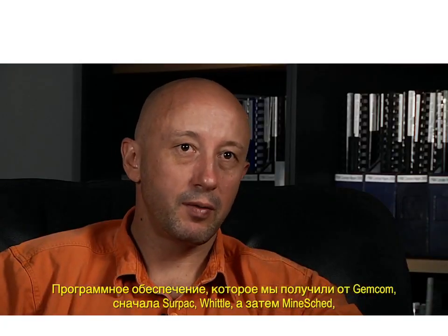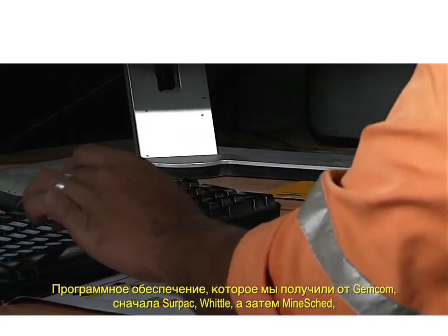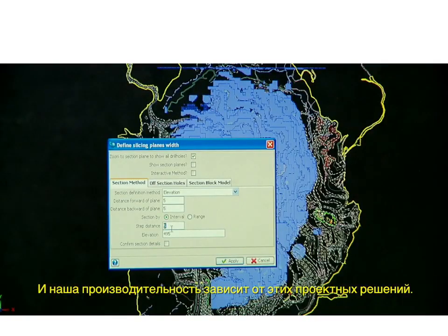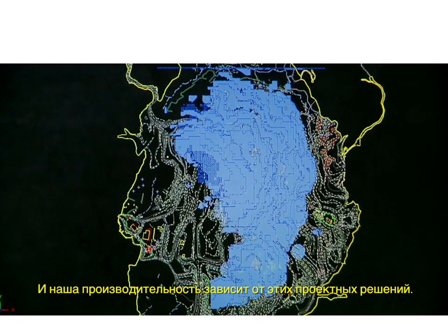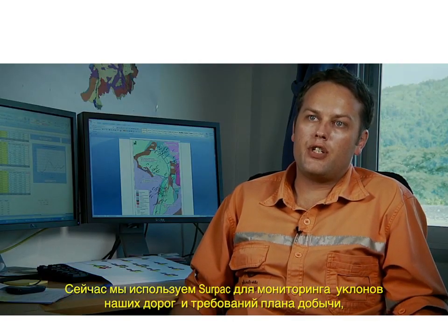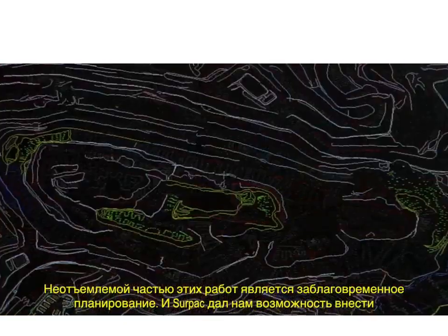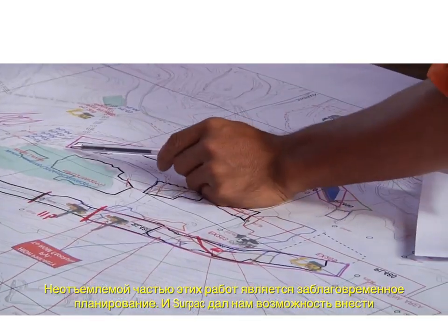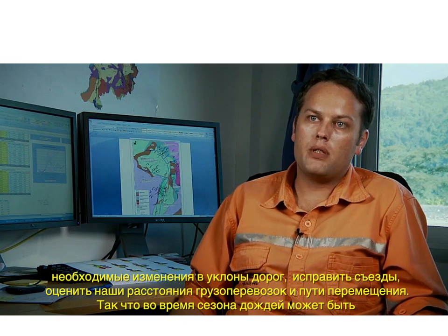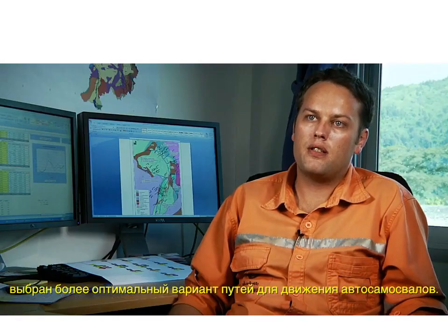The product we receive from Gemcom, which would be Surpac, Whittle, and then Minesched, is very much dedicated to our mining operation, optimization of that, and our productivity based upon those designs. We currently use Surpac for looking at our ramp gradients and our sheeting requirements leading into the wet season as well. And part of this is to plan ahead. So Surpac's allowed us the ability to fix our ramp gradients as needed, to fix our switchbacks, to look at our haulage distances and the requirements, particularly for sheeting requirements, so that there's better trucking surface throughout the wet season.